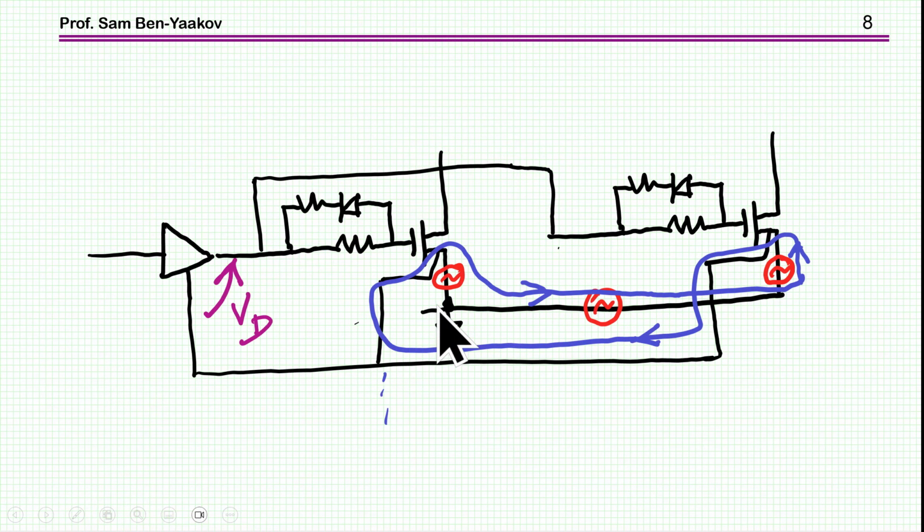Now there is a problem here because of the voltage drop here, you have noise here, and all this will cause a circulating current in between these two branches here, which are in parallel, which again will corrupt the signal that the gate to source is seeing here and the gate to source is seeing here. So you are losing sort of the advantage of the Kelvin connection.